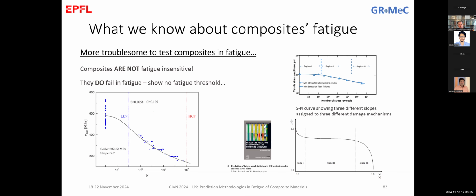We have the mechanism shown by this diagram, where we have the damage accumulation in the material that leads to stiffness degradation. But in some cases, we have mechanisms that increase the stiffness, like the reorientation that we've seen before. So when you have material with fibers that are oriented with the load, this means that the stiffness is increasing. And then at the end, the behavior that we see here is a synthesis of the effect of these 2 mechanisms.